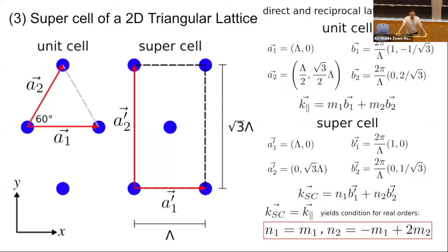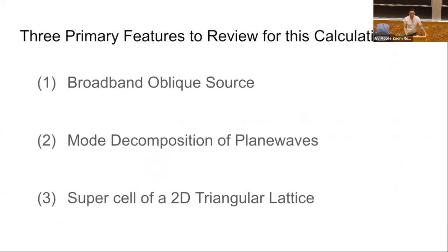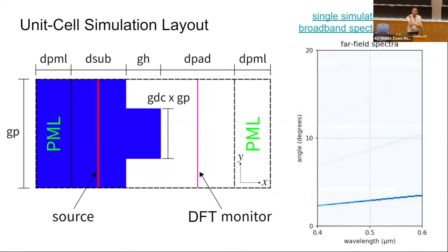Okay, one question actually I want to discuss is, there are other ways of computing diffraction efficiencies using other numerical methods. So a popular one is known as RCWA, and the package that's widely used is called S4. So that's a frequency domain solver that's very efficient for these kinds of calculations because it exploits the fact that they have these constant cross sections, right? Whereas in FDTD, you have to do a volume discretization using these voxels, right? So the entire computational cell has to be modeled using potentially a large number of voxels. In RCWA, you just model the actual constant cross sections, which is much faster for these kinds of problems.